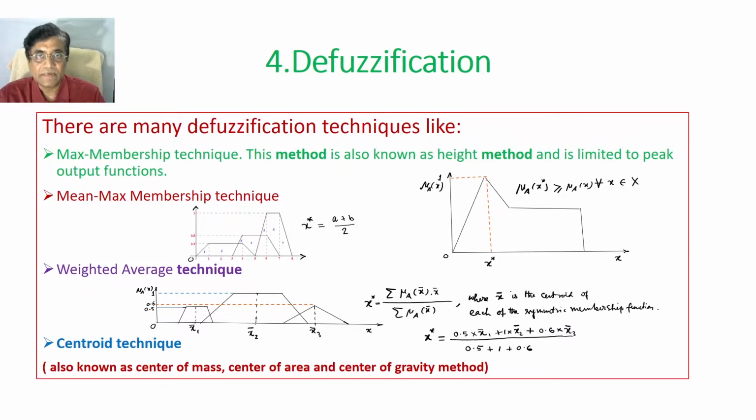fuzzy inference system. So the basic steps are, you will have to identify inputs, and once you have identified inputs, then you will have to enter the fuzzified zone by fuzzification, right? How do you fuzzify? By designing some membership function, okay? And the inputs have a membership function. Now they are fuzzified inputs. And then what you do, you capture human knowledge in the form of if-then rules, okay? And then allow those rules to be executed or fired.